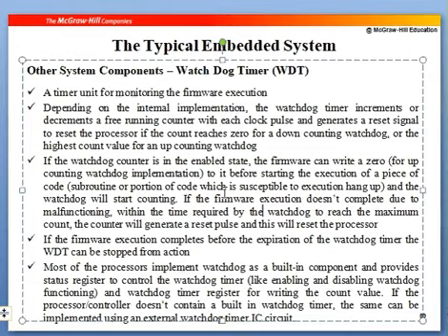ESP8266 module. When you purchase that online, initially there will not be a firmware dumped into it. So what you have to do is search for the relevant firmware for your hardware. The hardware specification will be given, and once you know that specification, you can search for the firmware. Then you can even dump the firmware. Once you dump the firmware, you can interface this ESP8266 module with your microcontroller like Arduino for communication purposes.